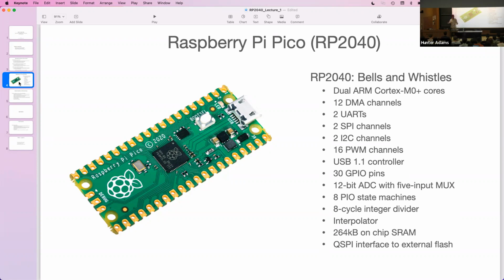For example, a VGA screen, which some of you may know requires a 25 megahertz clock, right? So that's a fast interface, and these PIO state machines allow for you to build that so that the RP2040 can communicate to a VGA, which makes our computer graphics experiments really fun, incidentally. In years previous, we've used the small SPI TFT displays, which are cool, but now we get so much pixel real estate, gorgeous 640 by 480 VGA screen. So in any case, we'll talk about these a bit. They're a little niche, perhaps, but they're cool enough that you'll have to indulge me at least a couple lectures talking about how interesting these things are.